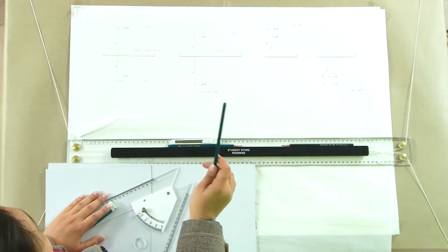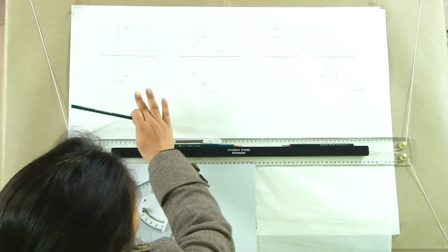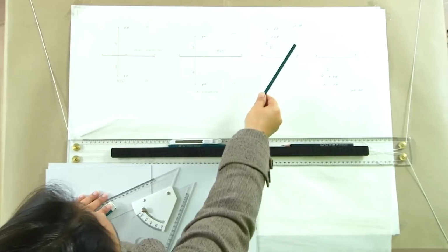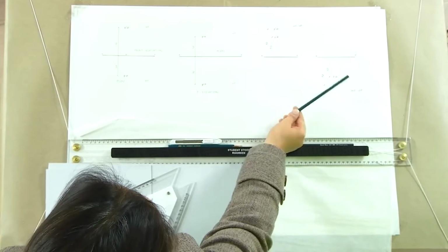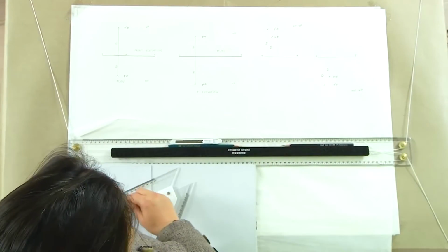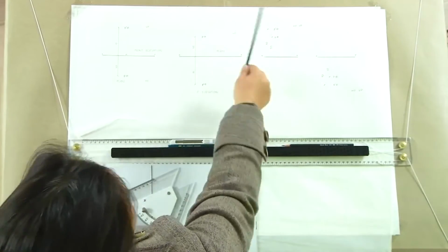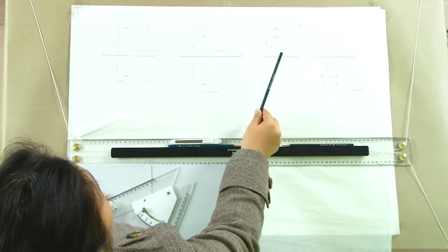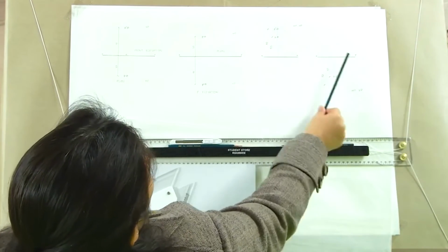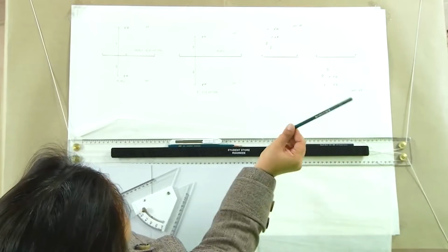Now, one thing which becomes very clear from this drawing is that second quadrant and fourth quadrant are not very convenient to read, because the projections will intersect, they will overlap. That is why we do not use second and fourth quadrant drawings. We preferably go for the first quadrant or the third quadrant.